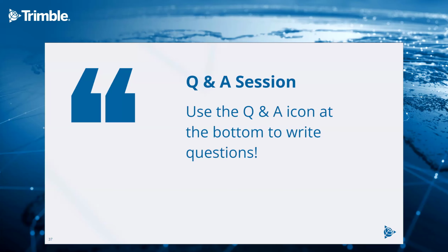So questions, I guess, on GCP, these always come up. I think you addressed it, that we can use them to check, but basically the question is, you mentioned no GCP is needed. Does it support the use of GCP when available? No, as I said, LiDAR QC right now does ignore GCP. So we cannot feed any ground control points into this process.